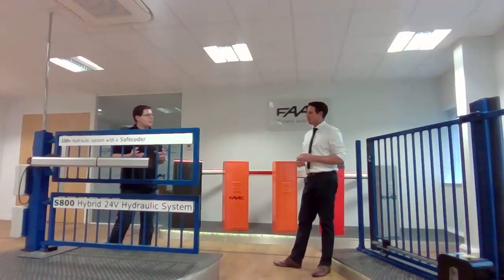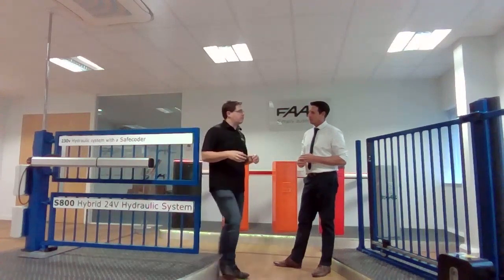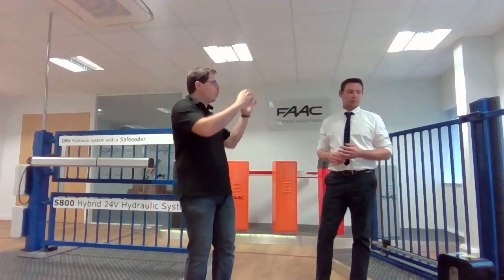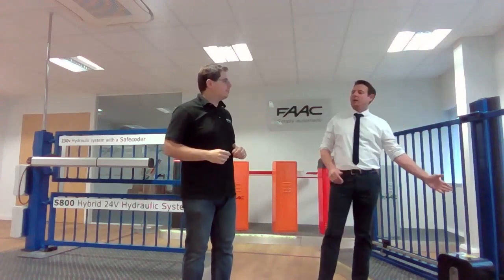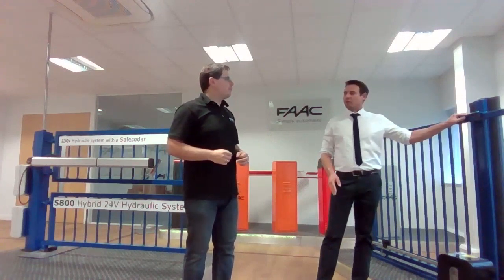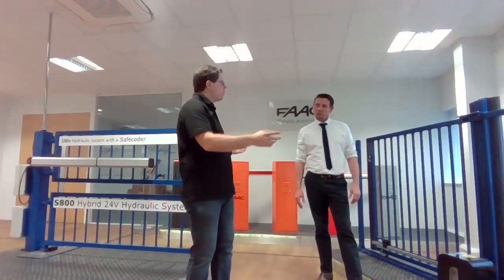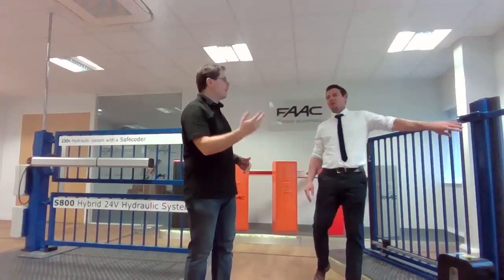They are the greatest risks, and the more recent news articles have highlighted that, especially on sliding gates where there were no physical stops fitted. So they might not have ideal bracing on the gate at the top, the rollers. So if we're looking at this, if you had the post there, you were safe, really. And with this sort of thing, you're looking for something that can retain the gate should this break. Exactly. So you've got multiple points there to keep the gate in place, but also when the gate's rolling along, the gate shouldn't be able to roll past. No, shouldn't be able to roll off. That'll be quite a bad thing if that happens.